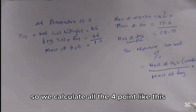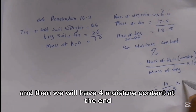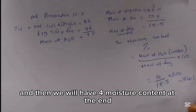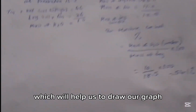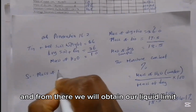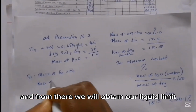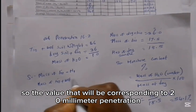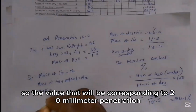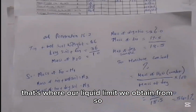So we calculate all the 4 points like this, and then we will have 4 moisture contents at the end, which will help us to plot our graph, and from there we will obtain our liquid limit. So the value corresponding to 20 millimeter penetration, that's where we obtain our liquid limit from.